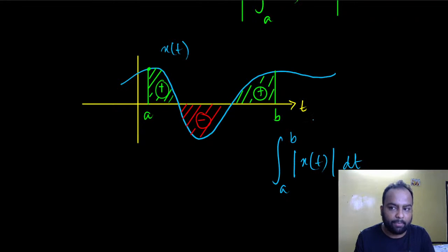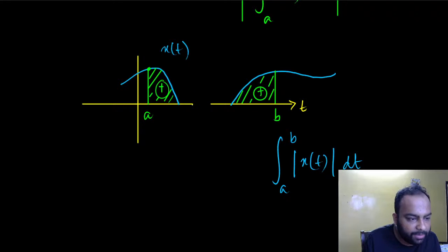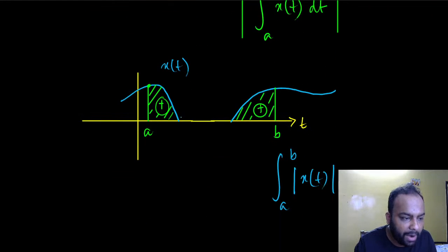Now, of course, what is a mod? Mod is like a rectification. So if the value of the signal is negative, that part will become positive, right? So this negative part of the signal will now become positive because of that mod here. Essentially, because of that mod, this part will get reflected and it will become something like that.